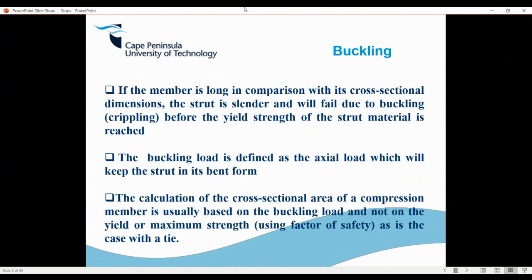So I mentioned the two factors: we check if the yield stress will be exceeded, and we check buckling. Buckling is key with columns, obviously a long slender column. We will unpack that later because there are different criteria you need to check. But anyway, it's a very, very important thing, especially in column design, so one must be aware if you're designing. In fact, if you think about a connecting rod, Rima showed them a machine design textbook, if you can recall.